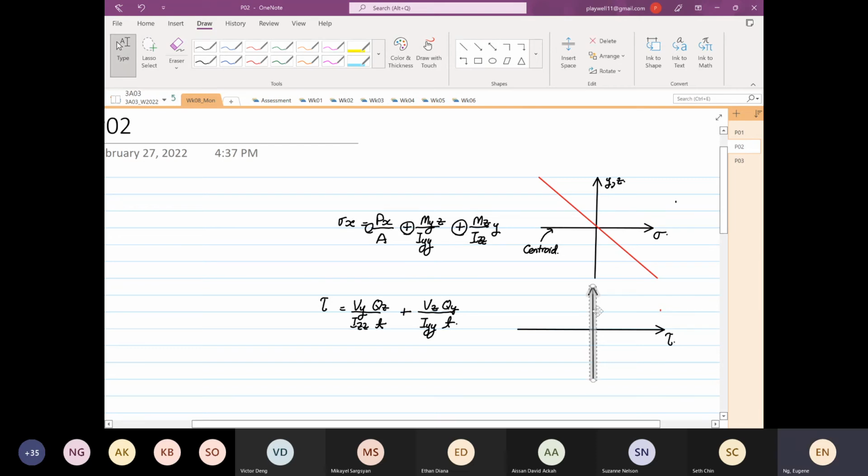And this axis over here can be our Y or Z. We tend to get a distribution doing this. And if this line is the centroid, so what we realize is that in terms of shearing stress, assuming uniform thickness, this is where tau max occurs, at the centroid.